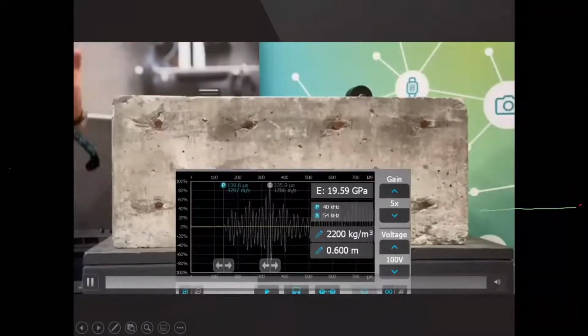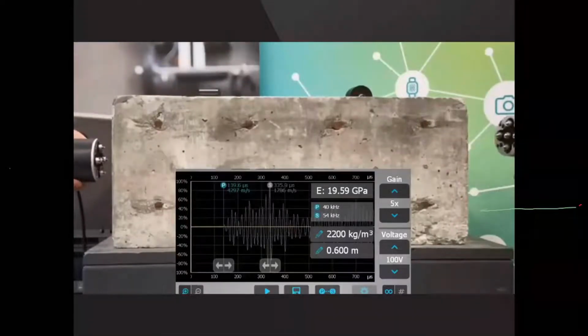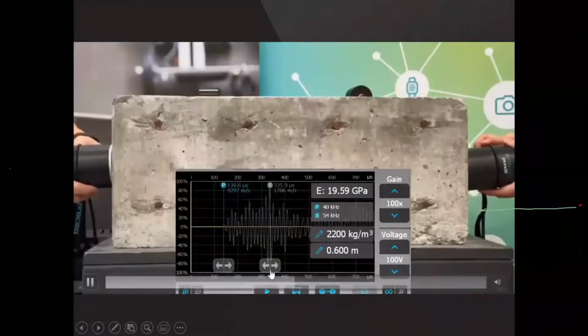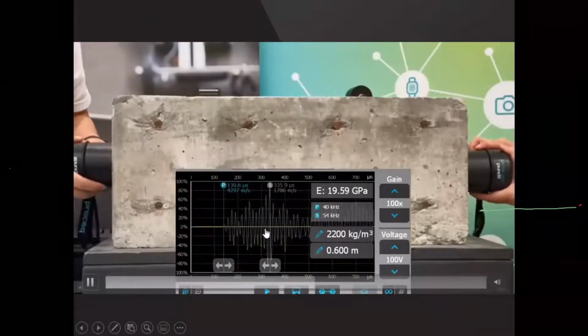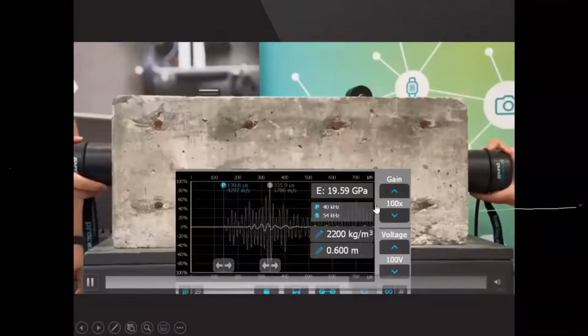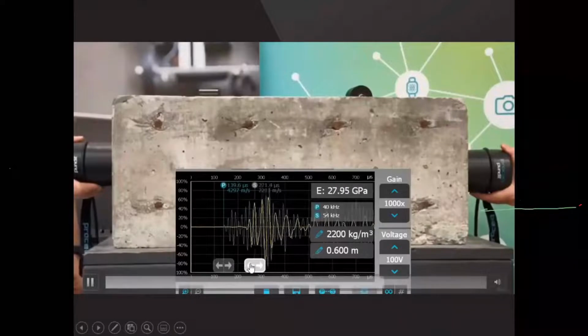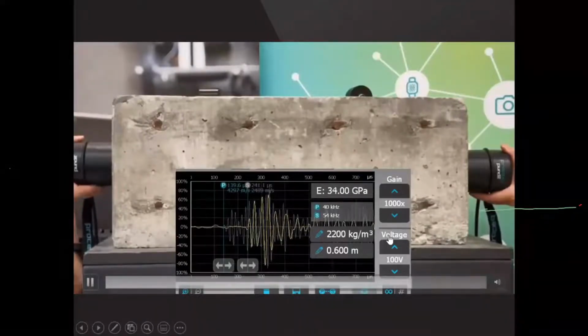right? And I'm doing the measurement at the same point again. Now I do the measurement of the S wave. You can see my S wave will start to come. It's a bit weaker, so I will increase my gain here a little bit, yes. And now I move my cursor to the zero crossing and stop the measurement. So that's all. My measurement is done, right?